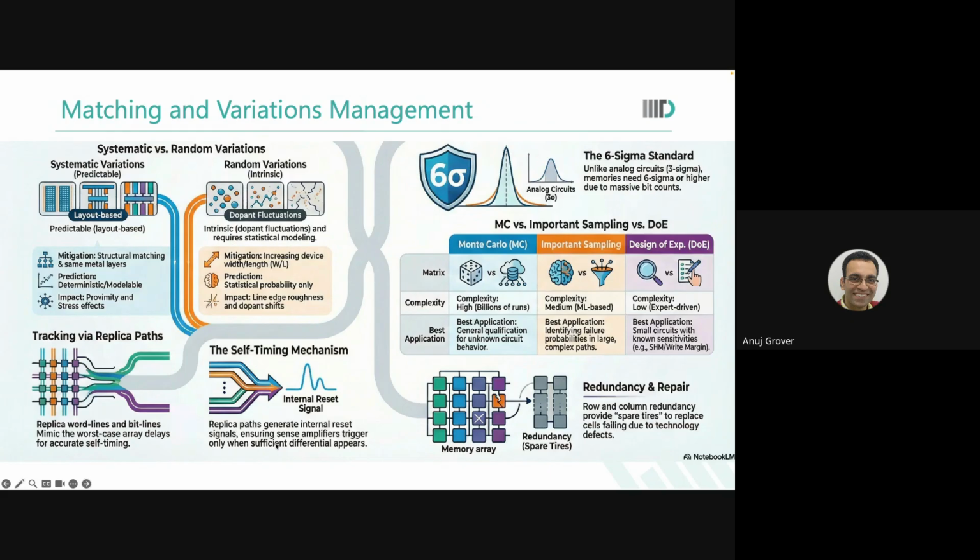Is that clear, everyone? Now we come to the next part. This question was, if I have this replica bitline next to the control region, then the precharge will turn on, but the sense amplifier is not being compared here. Maybe the rightmost sense amplifier has not yet decoupled the bitlines. So now this is a race condition.